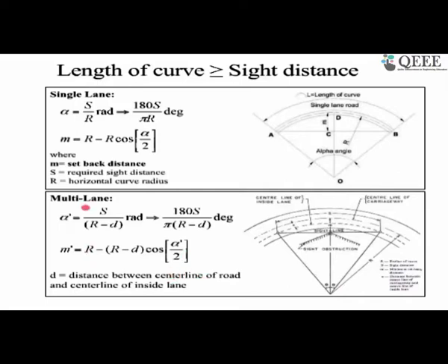That is how you are going to estimate. And once you put in there, this formula remains the same, r minus r cos alpha by 2, where this r is actually r minus d, because we were considering this distance. And then alpha is this angle, whatever is extended here, and based on that you are going to estimate. So here this figure is showing theta, but this is actually alpha, the same angle, theta is equal to alpha.